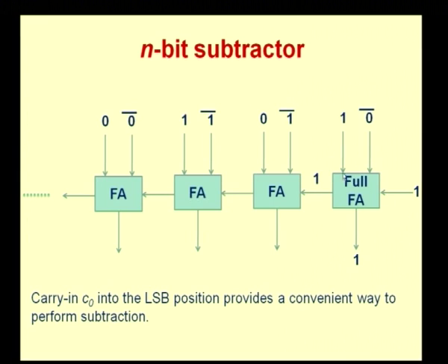I am looking at subtracting 0 1 1 0 from the number 0 1 0 1. Okay. So, what is it that I will have here? Look at this. Again, remember this is a full adder, right. So, what I have is 1 0 will be complemented and then 1 is the input that I am giving here. Remember C naught is set to 1. So, complement of 0 is 1. So, I have 1 1 1 as the input to the full adder, giving me 1 as the sum value